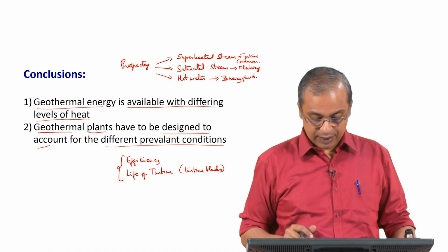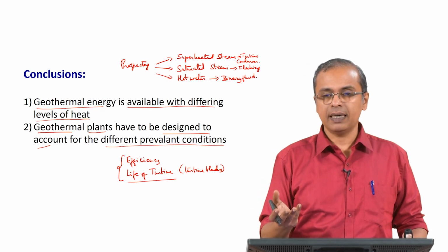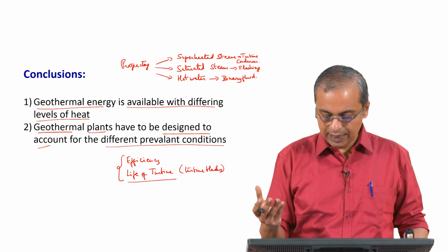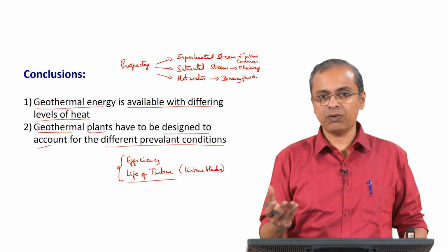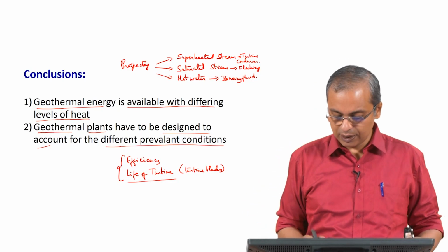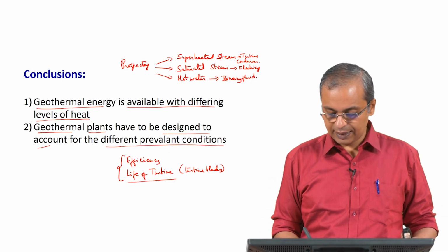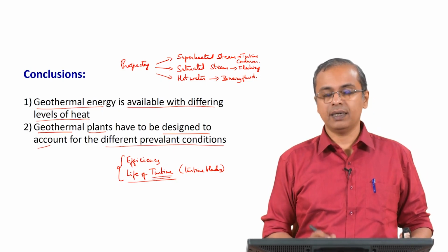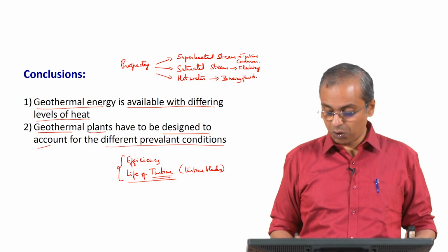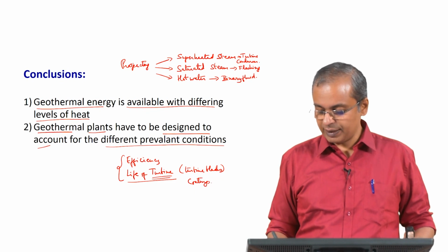you have to use. But if you look at the life of the turbine, you have to keep in mind that what comes out is not going to be pure steam, you are likely to have other things coming out. So your system should be capable of keeping track of that, to ensure that whatever is coming out is not dealing with a turbine which is incapable of handling it. Therefore there is a fair amount of material science with respect to turbine blades, and a lot of coatings are given, often ceramic coatings.